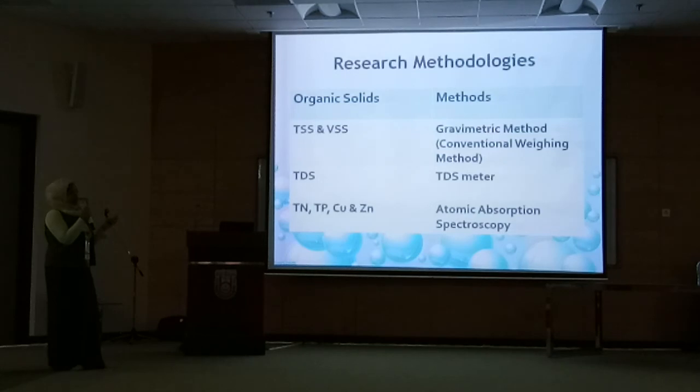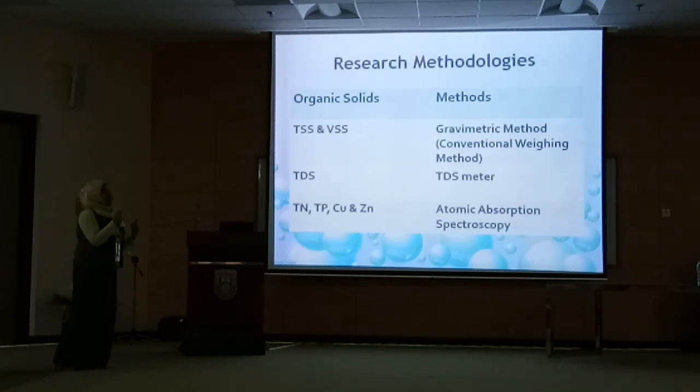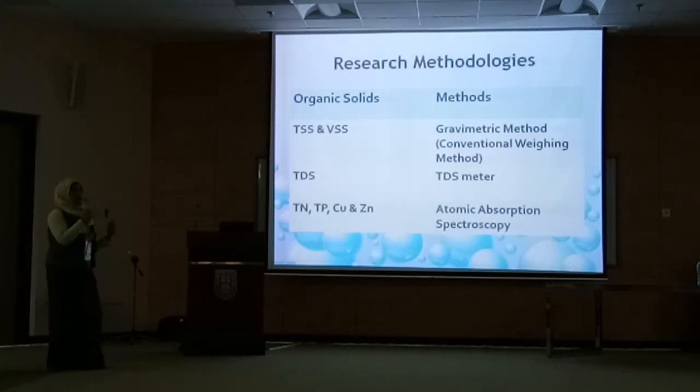TSS and VSS are series experiments. TSS is total suspended solids, which also includes VSS, volatile suspended solids. Volatile suspended solids are burnable, but still count under suspended solids. TDS, total dissolved solids, is more about ions and salts.